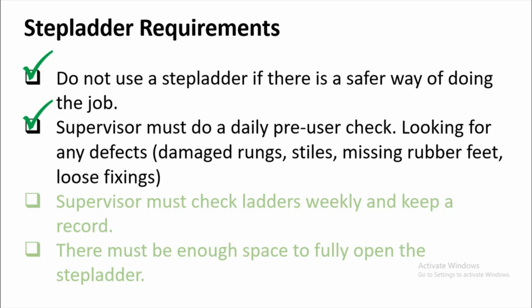such as damaged rungs, missing rubber feet, and loose fittings. So all must be checked. All parts of the step ladder must be checked to see that it is in good condition. Supervisor must check ladders weekly and keep a record of verifications for future reference.